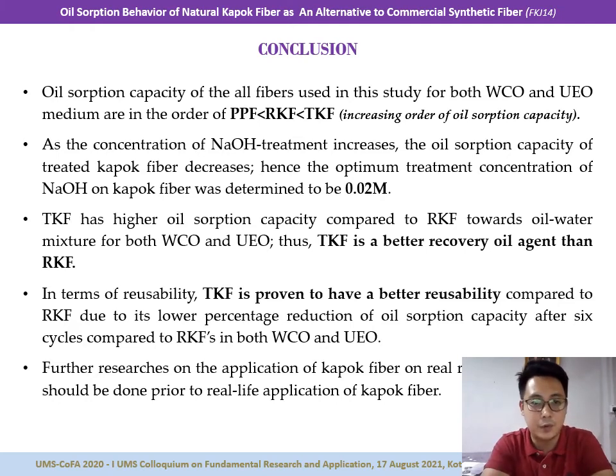So the treated kapok fiber has higher oil sorption capacity compared to raw kapok fiber towards the oil-water mixture for both waste cooking oil and used engine oil. Thus, the treated kapok fiber is a better oil recovery agent than the raw kapok fiber.